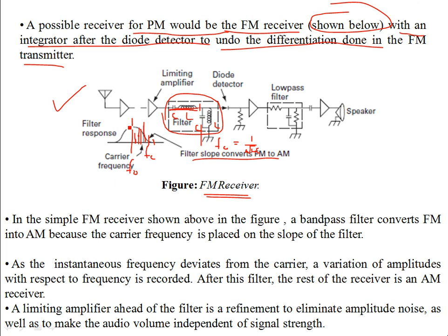But when you deviate from F0, the center frequency, the impedance of the series arm and the parallel arm takes over, and the frequencies start to suffer attenuation loss. On either side of F0, the impedance of the series inductor increases, and you have a decreasing, attenuating gain response of the filter. So it's a bandpass filter. This filter is a bandpass filter.